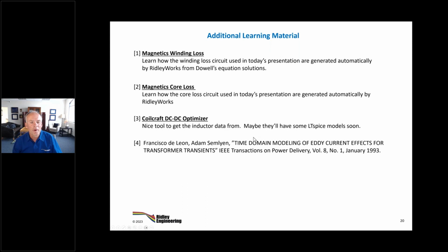And then for people who want to dig a little bit deeper, there's our proximity loss modeling, and the modeling with a fractal network to match the eddy current losses or the proximity losses. This was first done way back in 1993 in this paper, and I've seen at least 2 other people doing the same thing in industry.